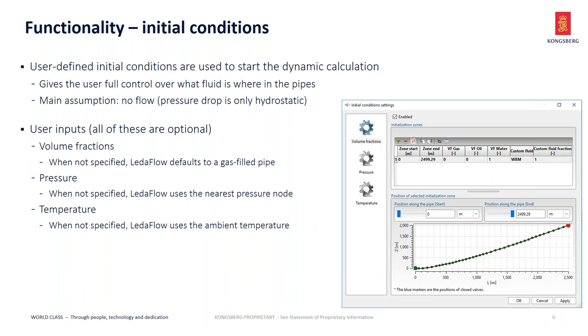But if you want something special, like in this case, we want to put drilling mud in the well, then we, of course, need to specify volume fractions. It's also possible to specify the pressure and temperature, but we'll not use that in the current demonstration. Okay, then we get to the demo.